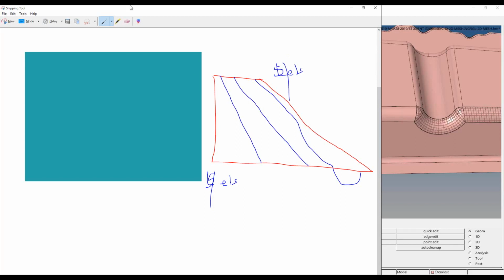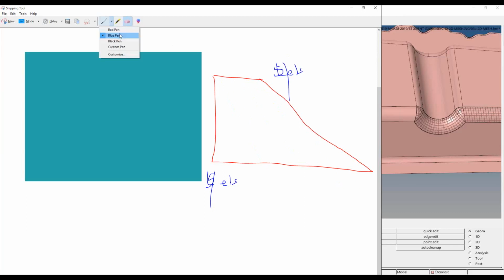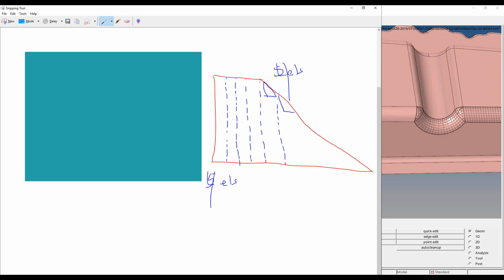Four elements, looks beautiful, right? But maybe you don't want this weird skewed angle thrown into your mesh flow. So sometimes what that skew setting does is ensure that we're going down in a straight line. It just might introduce a tria element along the way, and we'll see where it does that in a moment. It might introduce a tria element up here before it goes back to keeping it straight down. If that kind of makes sense.